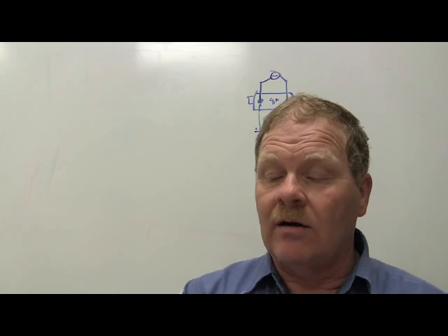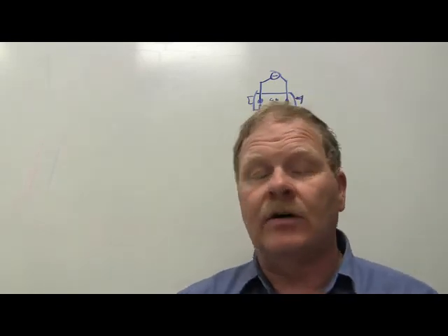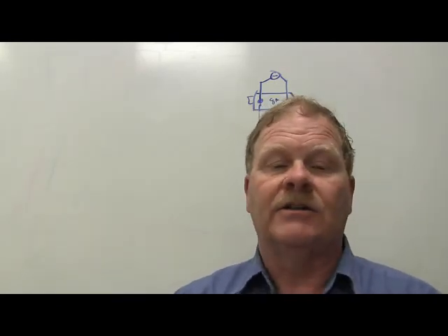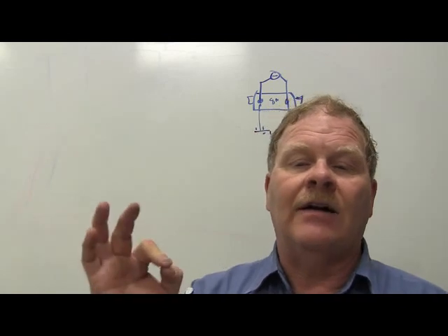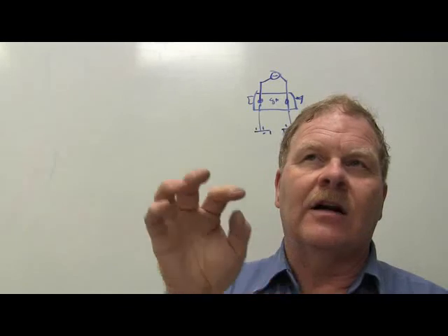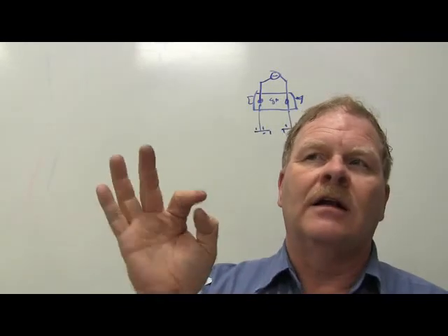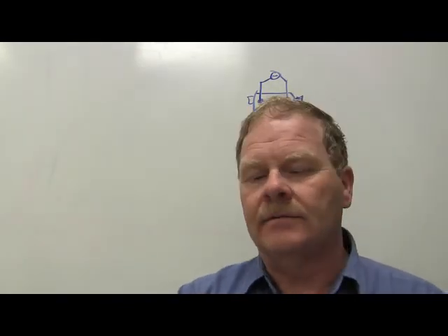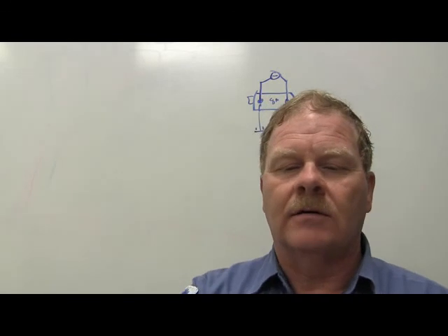If you're checking the quality of your ground connection, or performing the analysis of the input and output terminals on an electronic module, you're going to have to find not only the connector, but which cavity in that connector that wire goes through. Okay? It's really important there.